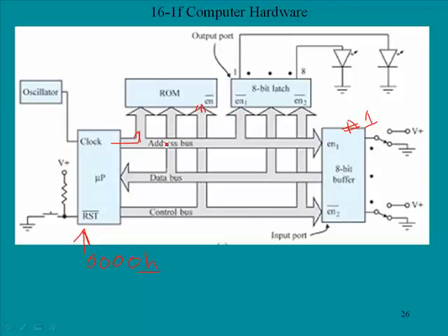Now out on the address bus, we send out this port number 00000001. Actually, it doesn't mention this in your text, but the address goes to every device in the computer, but only the one that has the correct number will actually respond. So it's on the address bus, it says device number 1, which happens to be this device.